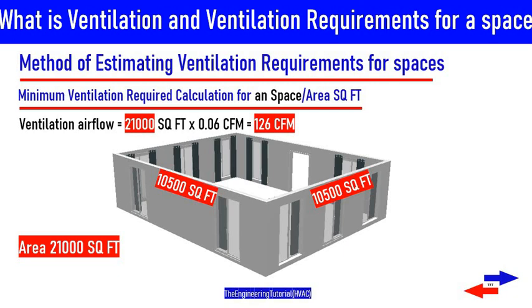So the 126 CFM is the amount of outdoor air required based on the area of that office that we have just calculated.